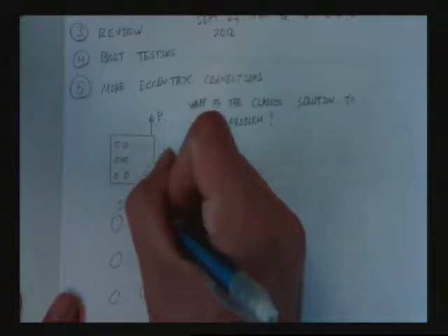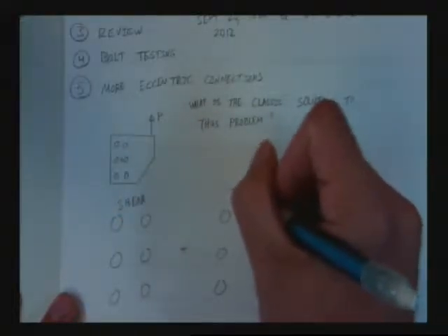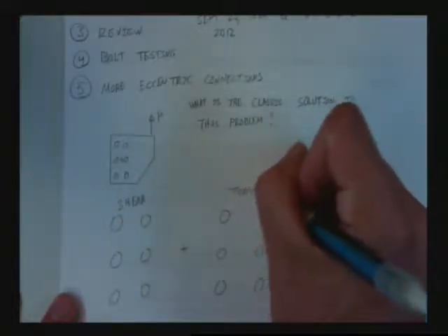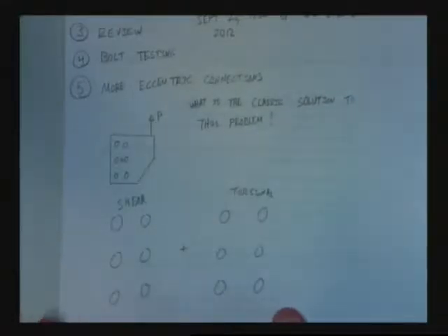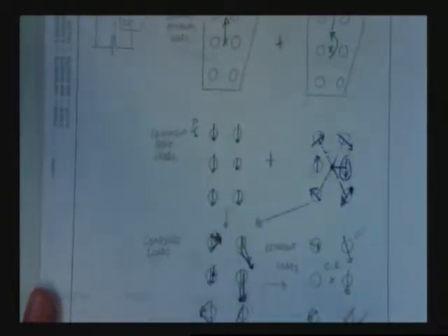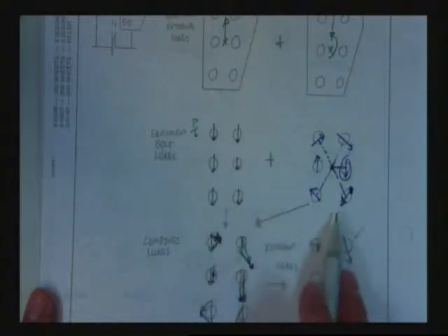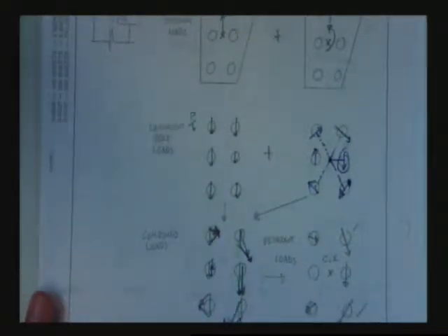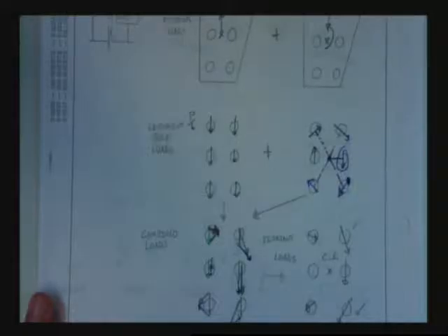Well, you break it up, right? You break the load up into some kind of shear component and some kind of torsional component. And hey, we did that. Boom! It appears magically. We had the shear component, we had the torsional component. We added these two components together, got a resultant from each one of those, and it looks something like that. So this is what the stresses look like, right?